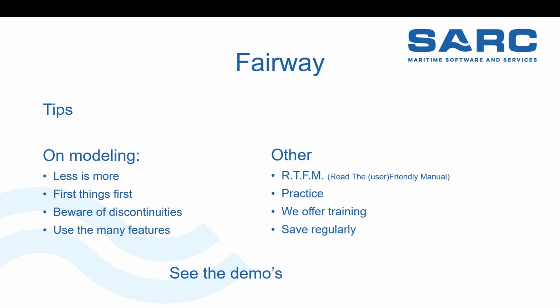Beware of discontinuities. We see a lot of, I will give an example later on, but if your flat side goes straight up, then the next buttock will have a continuity problem there, because 1 millimeter in, it should either have an infinite radius, infinitely small radius, or you have a discontinuity. That's actually what we see a lot and doesn't help. Use the many features, so it will pay to, well, check it out or call us every once in a while, or be here as you are today.